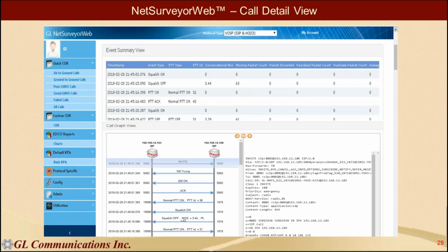Yeah, I think we can calculate the audio level. One thing Srinivas mentioned, I'll reiterate: as these sessions or calls are happening, if a PTT session is up, you're able to look at the spectrum analyzer or the oscilloscope in real time and get a real-time look at what the levels look like. But if you come back in a post-process mode and want to see a session that happened an hour ago, we can provide that average audio level for that session, but at the moment we are not putting that in there. But it can be done.